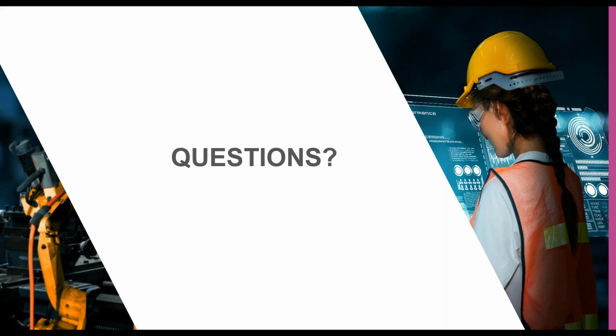Otherwise, if you change the native accuracy of the model, you will have issues, because Creo will try to merge the surfaces, and because of the accuracy, you will end up with many failures in the surface, and you need to merge everything step by step using the different techniques we used today.